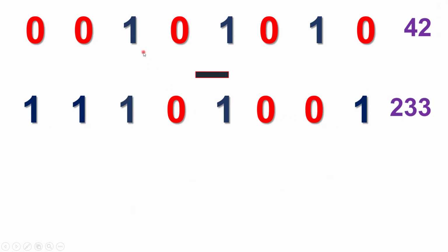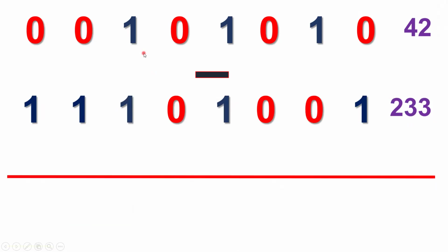So you are subtracting B from A. And for the difference you first start with the LSB, 0 minus 1. Obviously, 1 is greater than 0. The 0 has to borrow 1 from its next bit, that is right from here. So first, we see that it will borrow this 1 from the next bit, and therefore this 0 will become 10. In decimal, it is 2. So 2 minus 1 will be the difference output, 1, that we will write here.